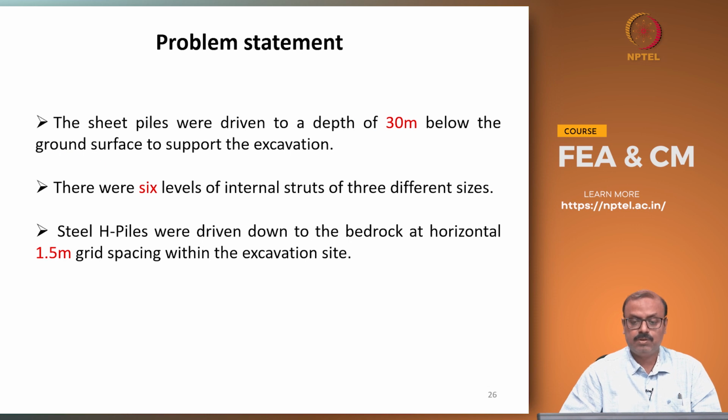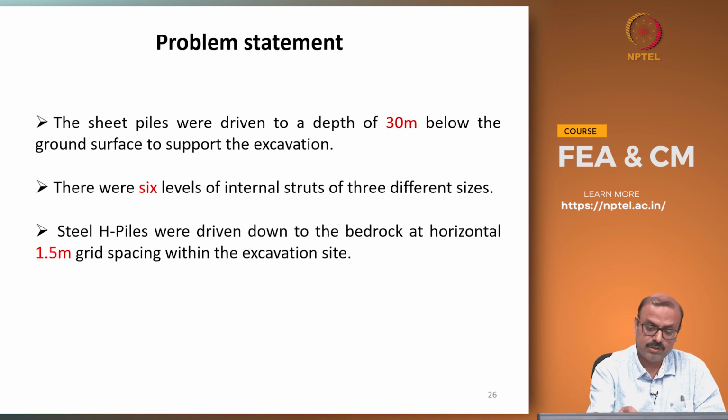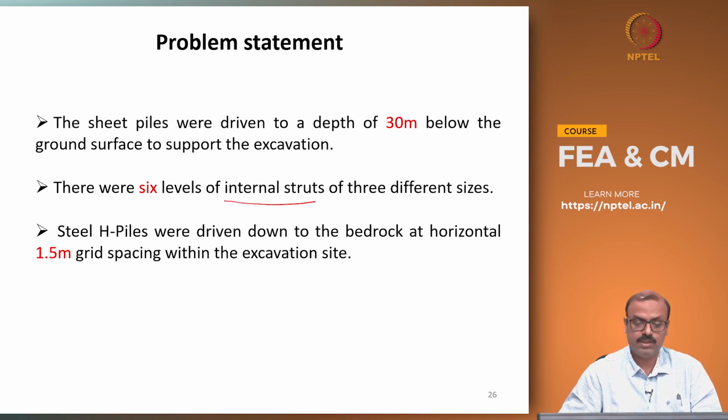The sheet piles were first driven to a depth of 30 meters below the ground surface to support the excavation. As I said, the top layer is a soft clay, so you have to really go deeper to get proper anchoring of the sheet pile. There are 6 levels of internal struts. So, you have a strutted excavation at 3 different sizes.